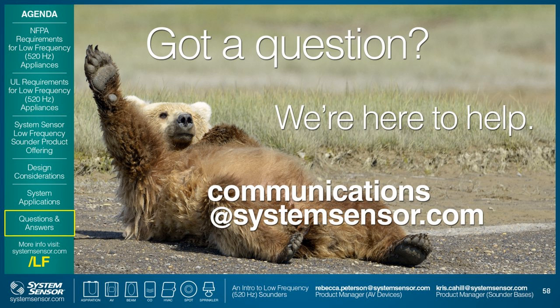Okay, very good. Maybe one more here. Will the sounders of low frequency be required in hospitals or other healthcare patient rooms or only in sleeping quarters? So maybe two questions there. Can you mix standard notification with low frequency, and then specific to a whole hospital versus sleeping quarters? Yeah, so you can mix them. As long as they use the same synchronization protocol, you can intermix non-low frequency with low frequency.